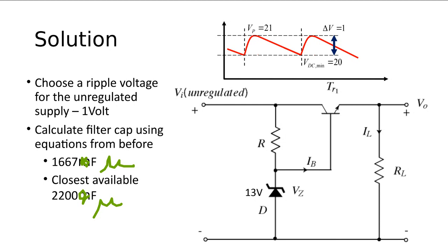Once you start to pull current from the power supply, the voltage from the unregulated supply starts to fluctuate. It starts at some value, which is a peak value. The capacitor charges up to the peak value of the rectified output, whatever that value is. But it discharges because you're asking the capacitor to supply the load. So the capacitor will discharge until the next charge cycle comes around, and then it will charge back up quickly to V peak again, and then discharge.